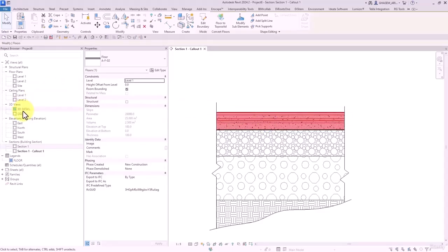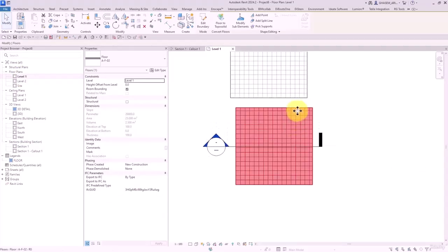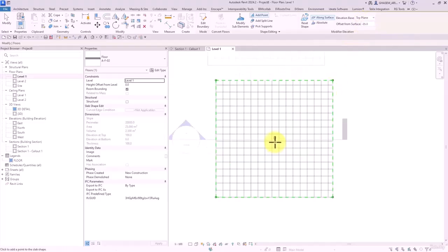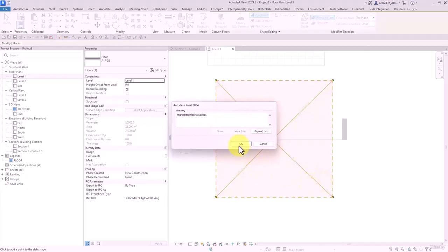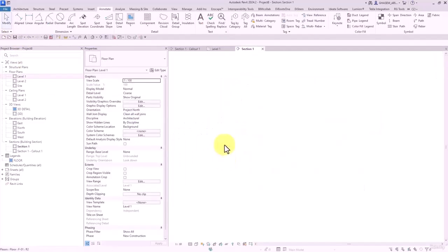Okay, after that, for sure you have some floorings in your project with slopes. Here in this level again, when I select add point, and here along surface, top plane, minus 40 or 35. Okay, now slope with these values. Guys, it's normal to face this warning the first time.